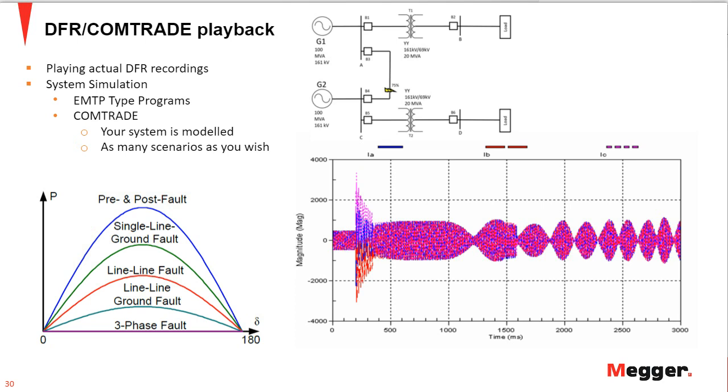COMTRADE gives you the actual form of the waveform that you know you are going to see in the real world. It gives you much more confidence that the test cases that you are using and generating are better, but it takes so much time to prepare, because unless you have real cases that you can actually use to test, or a library of cases previously built by somebody that they can give you